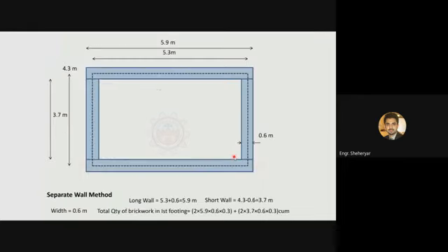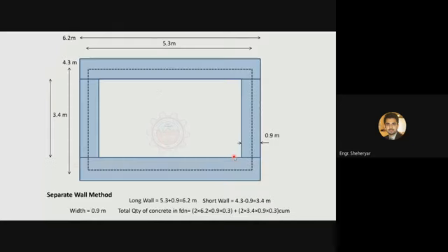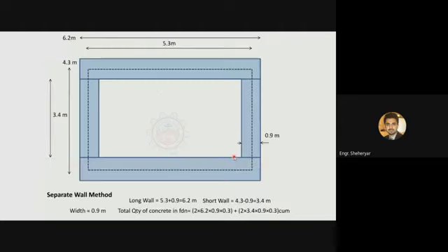Okay, considering this example, one thing you will observe is that when you are going from the bottom to the upper layers, and you are sticking to your long walls and short walls, not interchanging again and again, then you'll observe that the lengths of the long walls are reducing step by step, and the lengths of the short walls will be increasing. So let's observe this phenomenon.